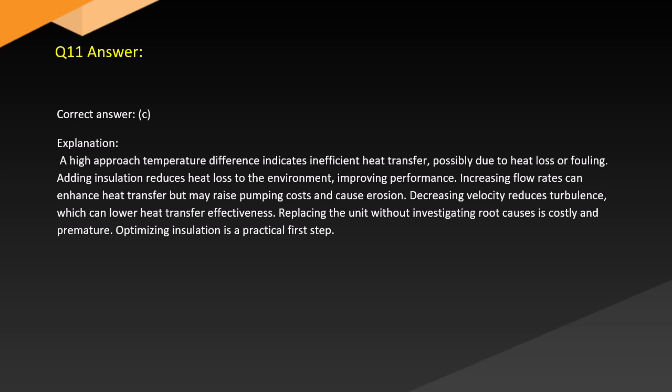Answer. Correct answer: C. Explanation. A high approach temperature difference indicates inefficient heat transfer, possibly due to heat loss or fouling. Adding insulation reduces heat loss to the environment, improving performance.